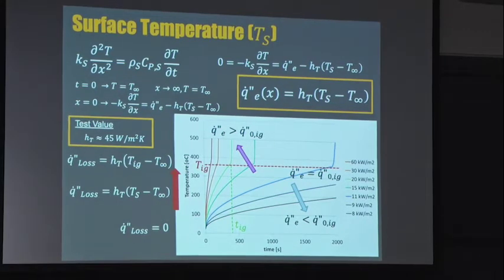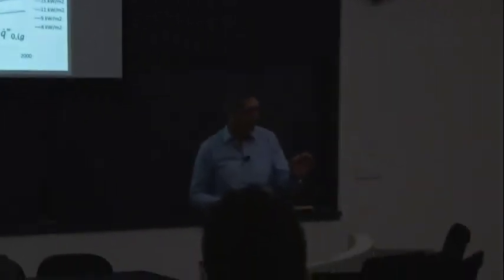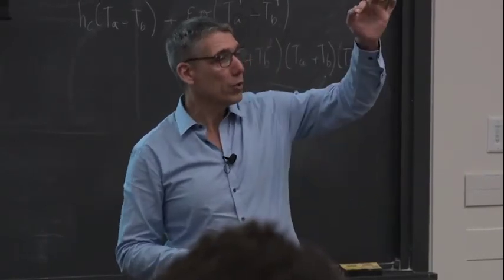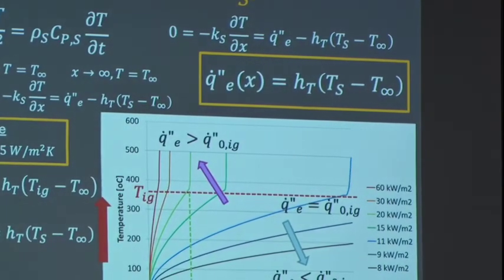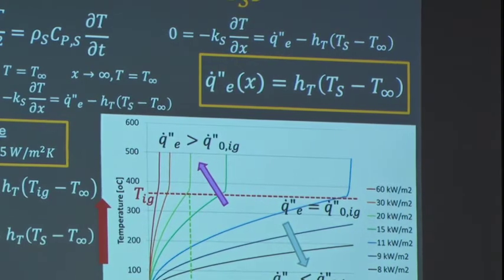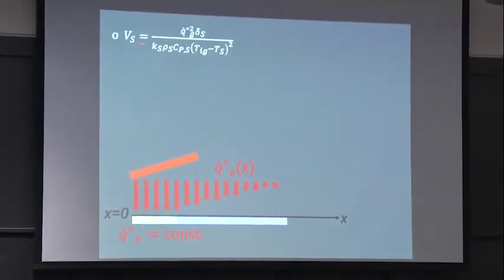Okay? Now, why does he do that? The reason why he does that is because that allows him to plot the flame spread as a function of the external heat flux. Okay? So, because he knows that the external heat flux is bringing you to thermal equilibrium, and therefore he can relate the external heat flux to the surface temperature, and therefore he can relate that to my solution to the flame spread equation. Okay? So, you're happy with this. Okay? So now, if I go there to my equation, this is my equation of flame spread. Okay? At each point in x, the flame spread velocity is this parameter phi, k rho c, T ignition minus T ambient. Okay? Ambient meaning the temperature of the solid, no?